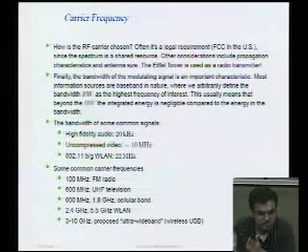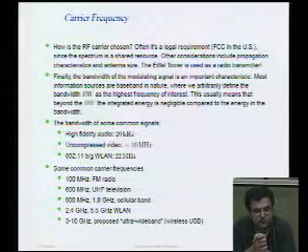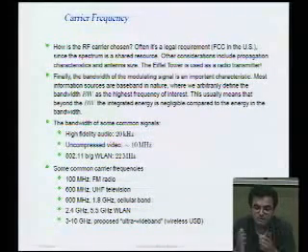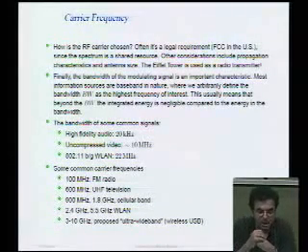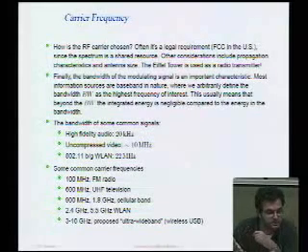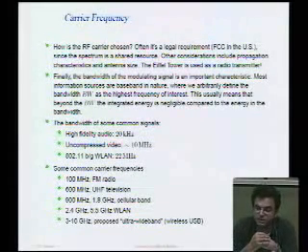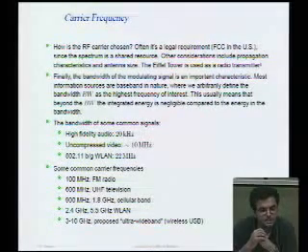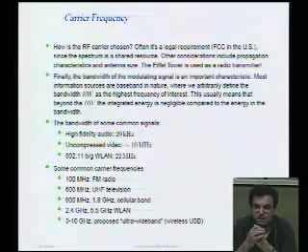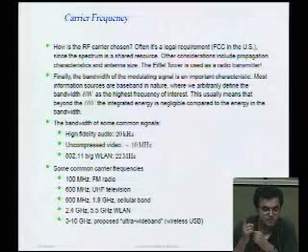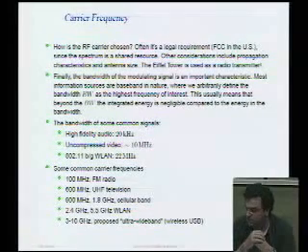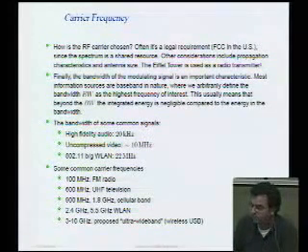So there's basically spectrum allocation that tells you, yes, this spectrum is allocated for, let's say, industrial, scientific, medical uses. You know, there's bands where you're free to transmit as long as your power level is lower than a certain threshold. That's a good example of the wireless LAN band. You guys can transmit as much as you want in the wireless LAN band. No one's going to come and arrest you because that's an ISM band and you're allowed to transmit. But your power has to be lower than a certain threshold. If it's above that, technically you can get arrested, or you'll annoy a lot of people who may beat you up. Either way.